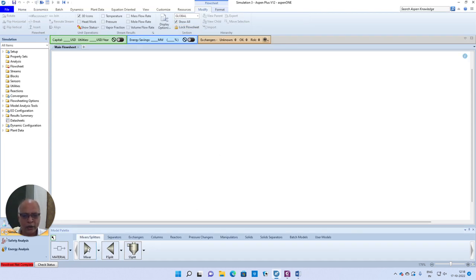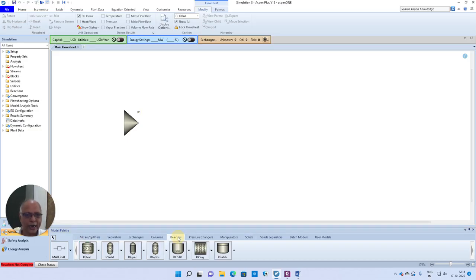and then create the flow sheet. So here, the composite of methane and ethane is mixed with air, and this is converted in a stoichiometric reactor, where complete combustion can be assumed. And what would be the combustion products we'll be able to get? Because 100% fuel is combusted, we are having excess oxygen, all the nitrogen that is inputted, along with the products formed, carbon dioxide and water vapor.